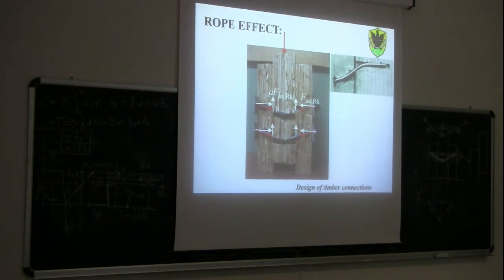What would be the difference between a smooth nail and a screw, in your opinion? If I had a screw here with all the threads, is the screw free to come outside? No, because the threads cannot move freely from the timber unless they break the timber.